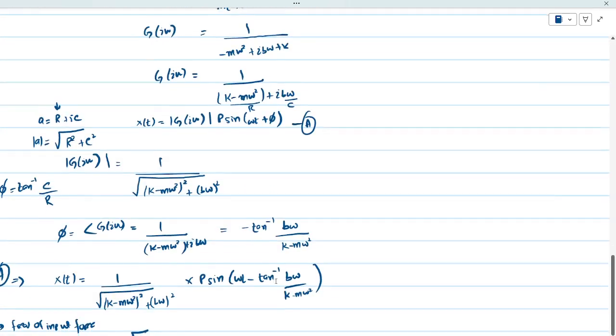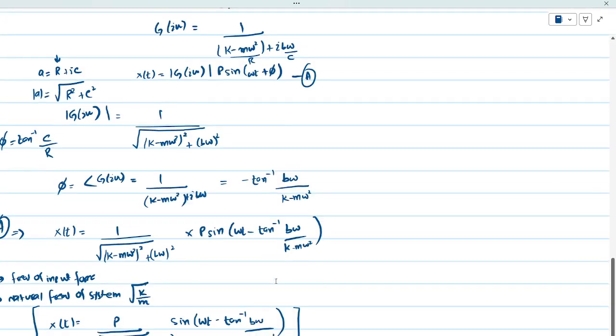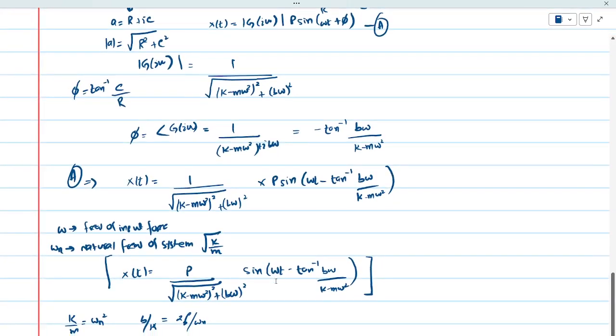After rearranging all the terms, we transform the whole expression into dimensionless quantities as much as possible. So we use the amplitude ratio, the frequency ratio, and the damping ratio, because they help us easily classify the system instead of calculating each and every variable separately.